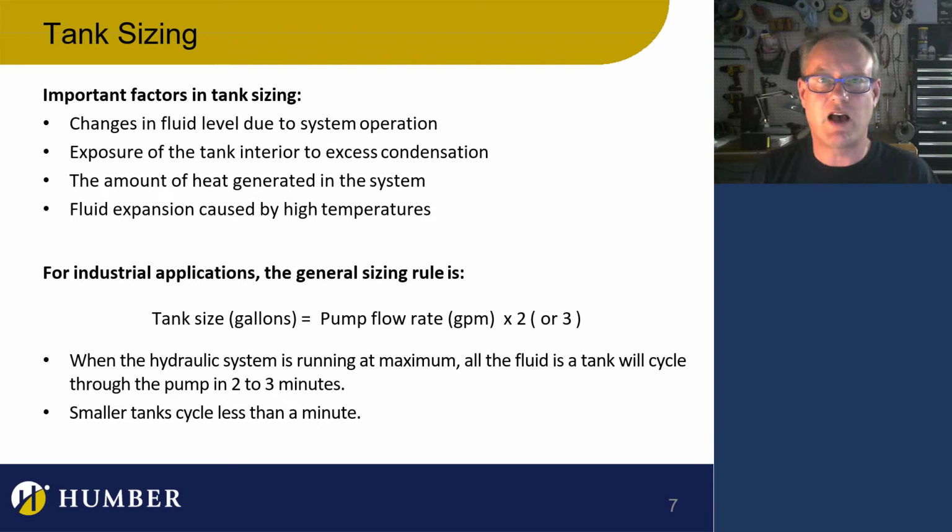So the tank itself is protecting the fluid that's in the tank from the outside environment as well. And lots of things can get in there, and we'll take a look at how we filter the fluid going into the tank. And then there's a lot of heat that's generated by the fluid. I think you understand that we have a lot of pressure losses in a hydraulic system. When the fluid's traveling around, we're losing pressure, but that means we're losing energy.